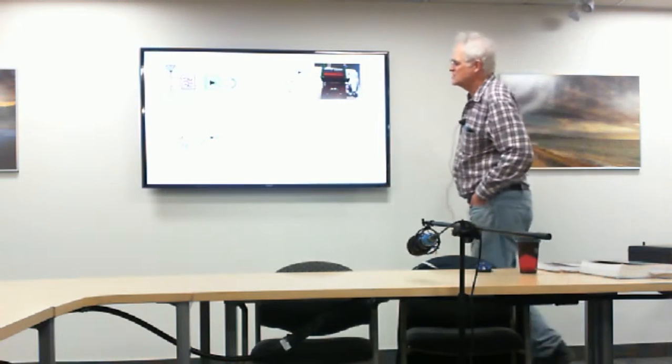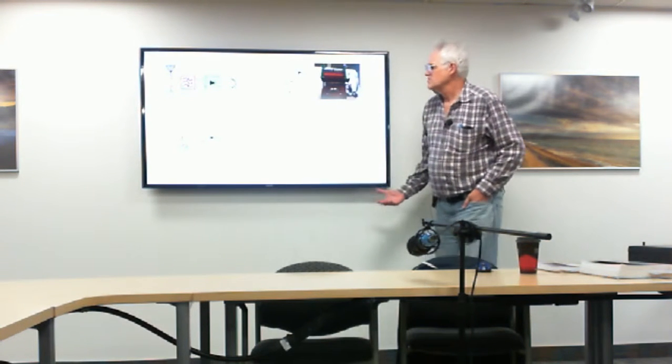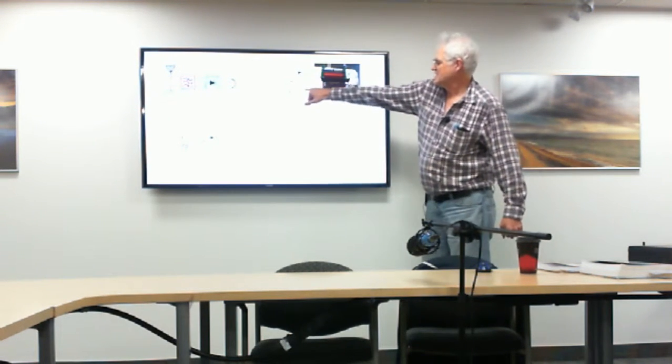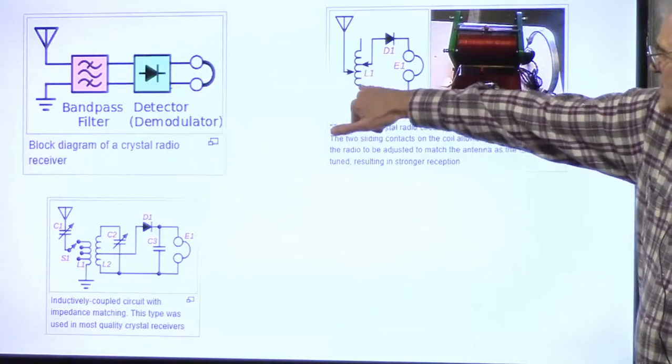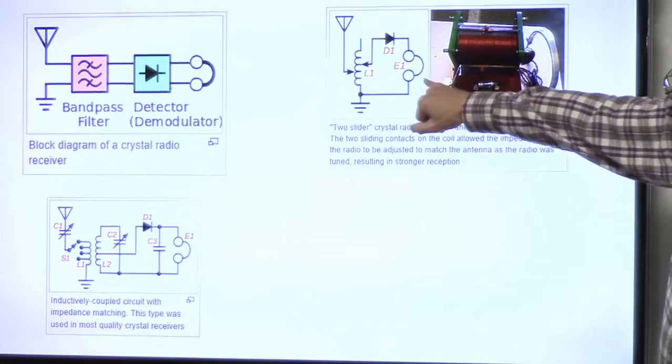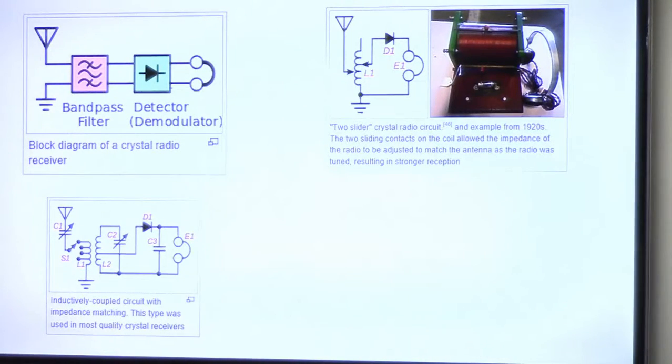Not necessarily on the test, but maybe a little bit of history. One of the very first radios that people used was the crystal radio. Some people weren't using a true crystal; it was just a variable inductor, a diode, and high impedance headphones. No power at all applied to it, it just picks up enough signal from the air to provide a weak signal into your pair of headphones.